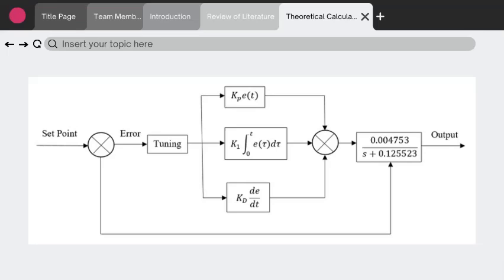As a result, TP was set to 85 degrees Celsius, and the model obtained for TB was adopted based on the observation from the plant operation that TB approximately equals TP. The Ziegler-Nichols (ZN) tuning method is applied for tuning the PID controllers